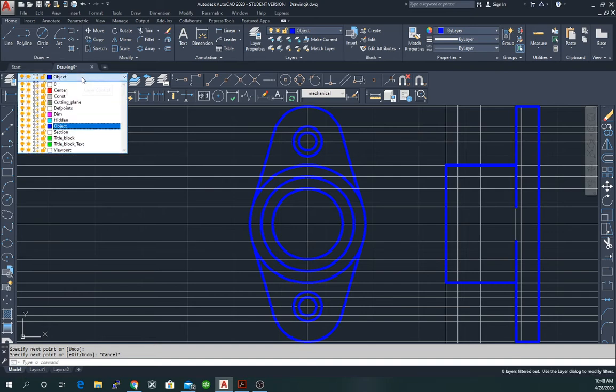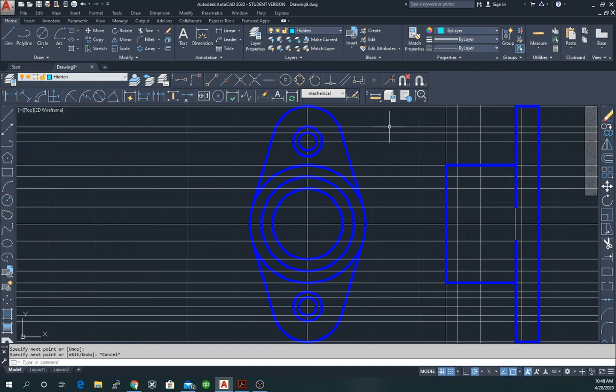So from here we need to now start putting in our hidden lines. And to put in our hidden lines, we first go to our hidden layer. And we have a large recess here that will hold, I don't know, presumably whatever this bearing is supporting. We'll start with a line, and that's going to start here. And then come down.